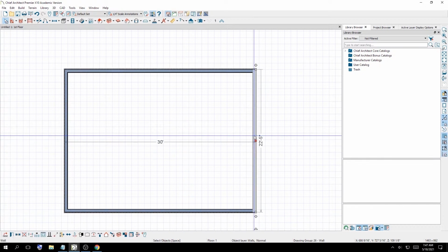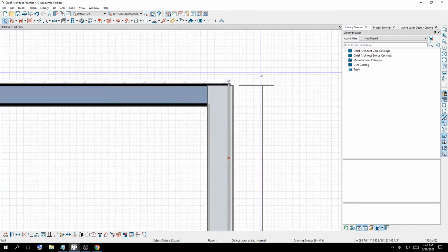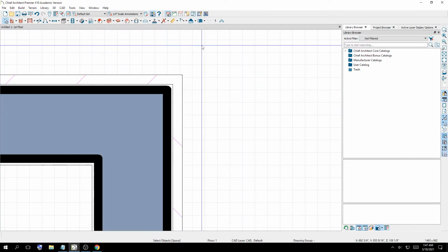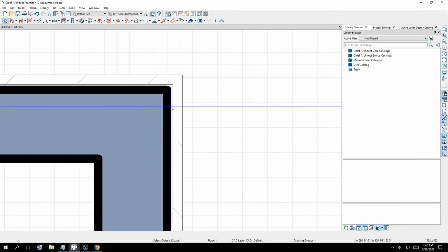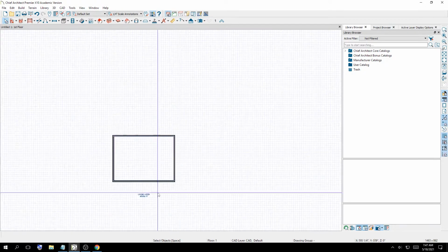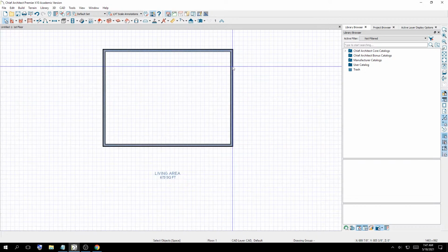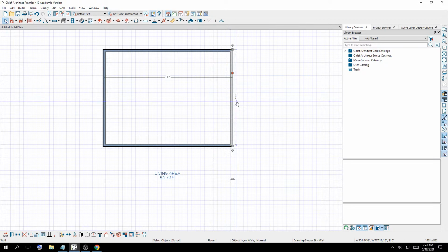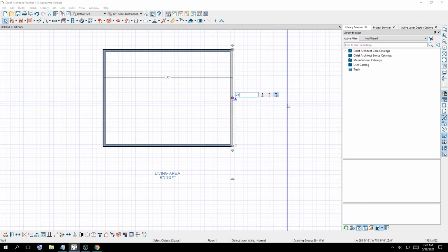So I'm going to click on this wall. As you can see, it says 22 feet 5 inches, and if you look at the leader lines, it is pointing once again to the walls, not the sheathing or the siding of the house. Okay? So it doesn't necessarily make a difference. I'm going to go 30 by 25. So if you click this and then click the number on the outside of your house, you can type in 25. Honestly, it doesn't matter what side of the house grows.